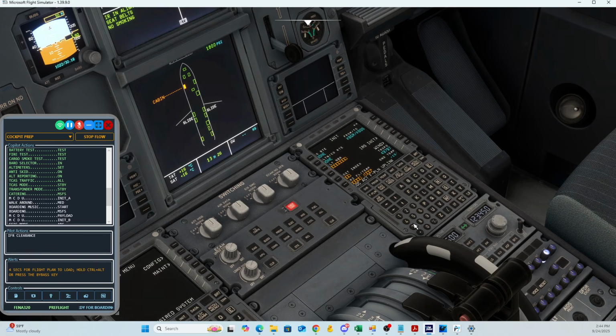You see that flight plan, that uplink is loading. We're just waiting for it to load in. And then he's going to go ahead and fill out the rest of the data. Remember, we said flight number is Delta 101, so there he goes, Delta 101. And he put in that cost index, I think we said it was 15. Yep, there it goes in. And then he'll put our cruise level, flight level 280.